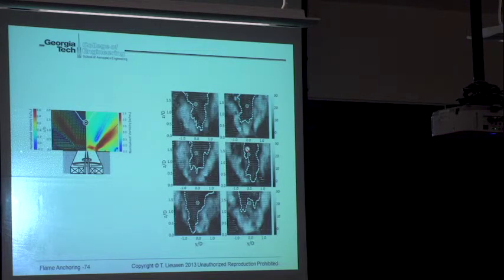And again, this actually goes to my other point, is presumably if the leading edge of this is where the velocity is 0. So if you're downstream of that leading edge, the velocity is going up, and it'll be a very high velocity, a velocity that's close to your nozzle exit velocity, maybe 50, 100 meters per second. If you're at the white, it's 0. If you're inside the white, it's minus. So pretty significant flow deceleration that's happening. But presumably the flame is going to want to be anchoring itself right around that leading edge.